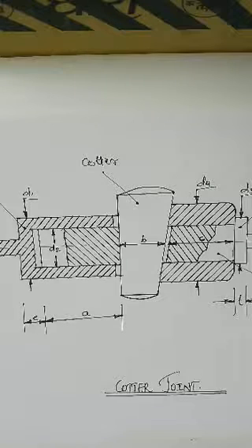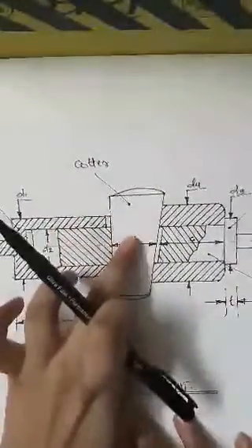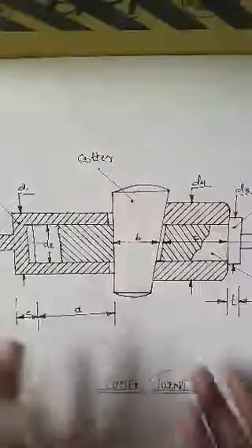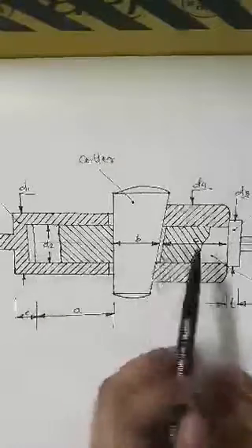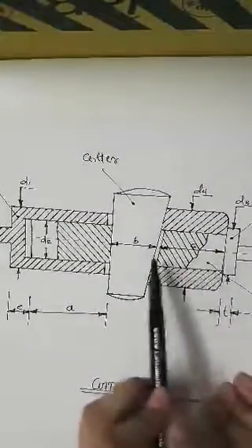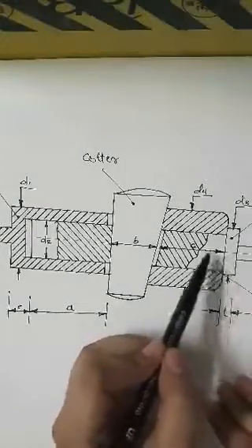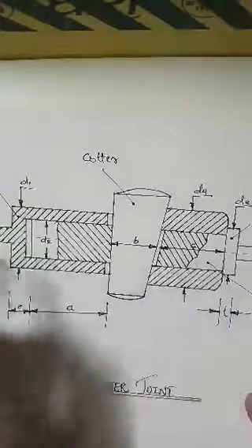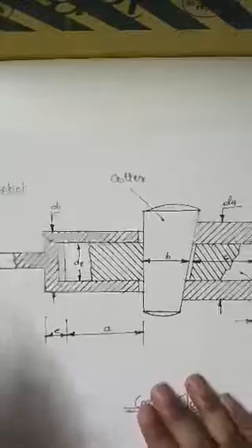First, let us see the parts of a cotter joint. The most important part is the cotter, due to this part the name for the joint is given, hence the cotter joint. Now there are three other parts as well. This is known as socket, inside which the spigot end inserts, and the spigot collar is the part which is at the end of the spigot end and connects to the rod, and it can be used for tensile or compressive loading.